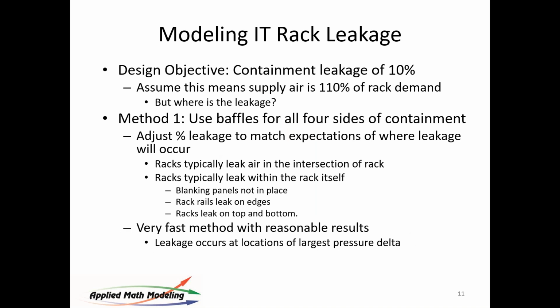And oftentimes the design community, the buyer, the customer, what have you, will say to you, oh, well, let's assume 10% leakage. I hear this a lot. The containment leaks at about 10%. And the question becomes 10% of what? Is it 10% of surface area? Is it 10% of total air supplied? This is not well defined by the design community.